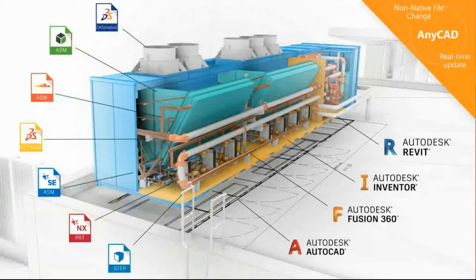The technology behind this workflow is known as AnyCAD, and it allows us to reference CAD files into Inventor from other CAD systems without file translation. This means that the CAD file can be edited in its original authoring tool, and when it's saved, an update will trigger inside of Autodesk Inventor. The benefit is that you can collaborate with designers who are using other CAD tools without having to convert files from one format to another.